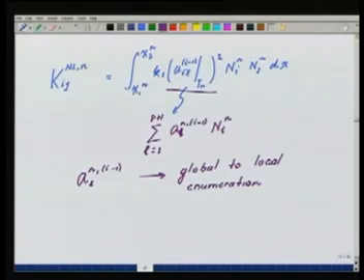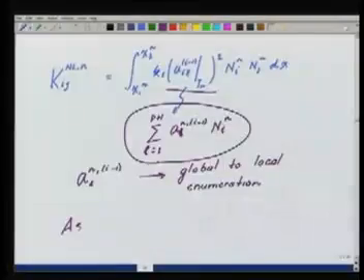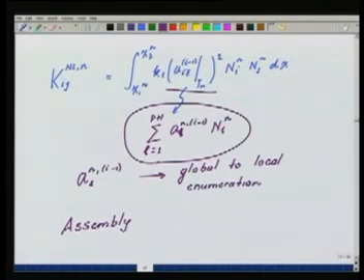Now we go to numerical integration. We evaluate this function at each integration point, find the square of it, multiply with the value of the shape functions N_i and N_j at these integration points, and do the summation as usual. So this will give me the element-wise nonlinear stiffness matrix. Then we follow the usual assembly procedure using the global-local enumeration that we had talked about till now.